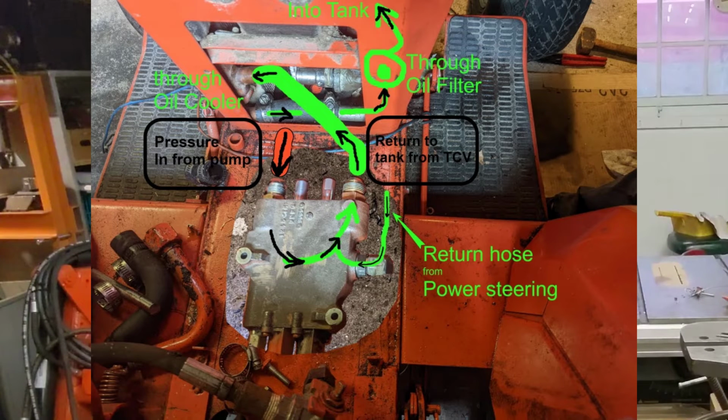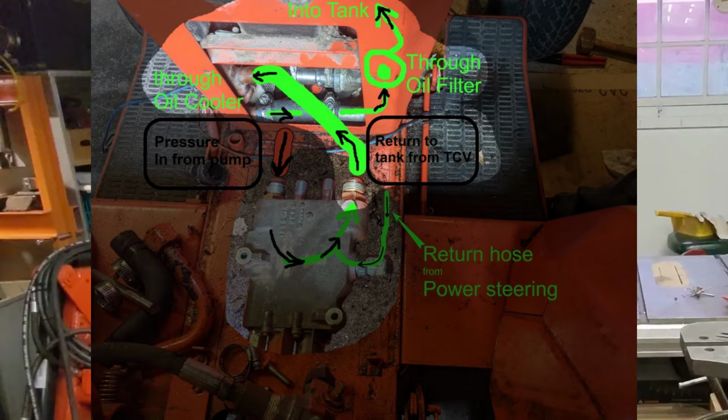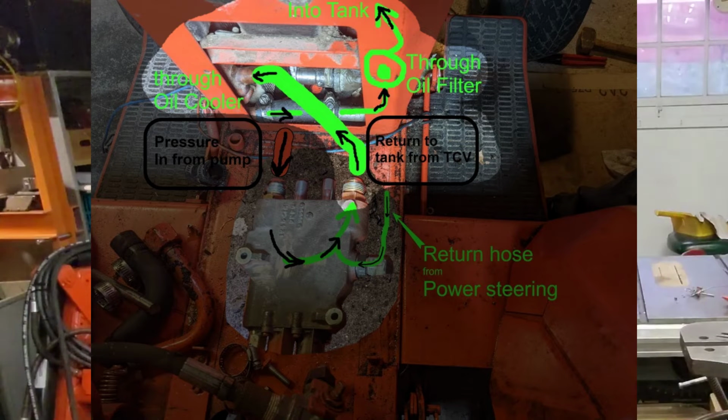In the old design, there are 3 lines connected to the travel control valve. The high pressure feed line coming from the pump, the big low pressure return to tank line heading up to the oil cooler, and a small low pressure return line from the power steering valve. That small line returned at the point marked PB, where it used to dump the power steering valve's return to tank oil into the low pressure cavity on the travel control valve, kind of using the travel control valve as a T. From there, the return to tank oil makes its way first through the oil cooler, then through the oil filter, and finally back into the tank.